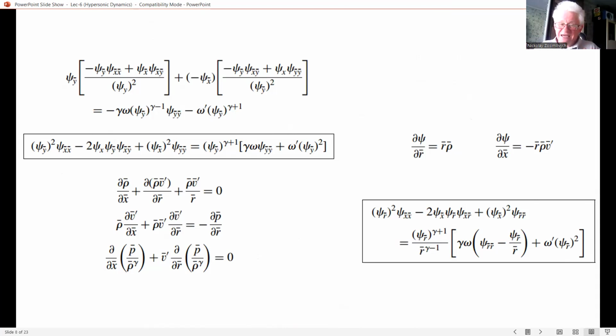And hence, our equation is of the same order of accuracy as the original hypersonic small disturbance equation. So once this last equation holds for two-dimensional planar flow, and hence it can be applied to two-dimensional shapes such as airfoil.